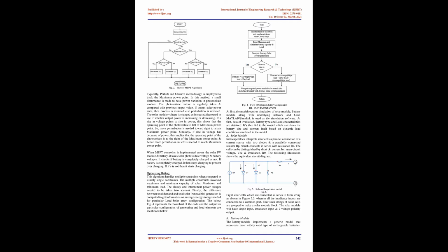The grid normally manages energy flow and controls the power and voltage, and may be isolated from the power system or interconnected to the power system at one single point. This single point of connection to the main grid is called the point of common coupling. In this method the progress is to be in the direction of common types of distributed grid. The control system absorbs the dynamics of the system by checking values of a few important parameters through sensors and changes the system to achieve the objective of stable supply.